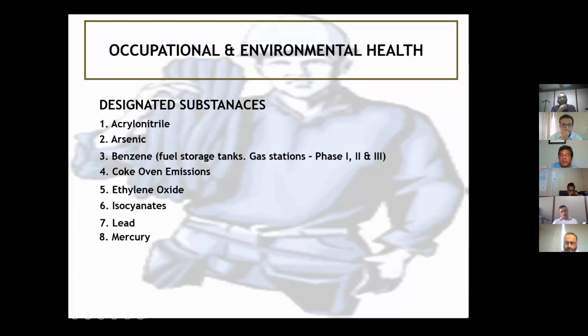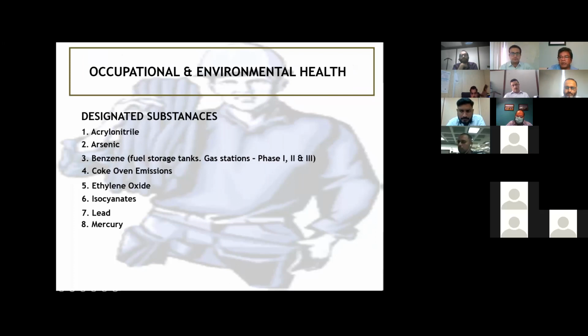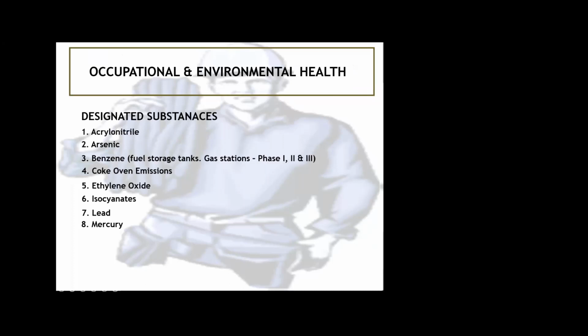People have been working in those labs, and the mercury gets trapped into the drains, let's say, the P-trap, in other words, so it does not flow with the water. If you open a trap, the mercury might be sitting there for the last 40 years. We have found mercury penetrating through the floor tiles, and sometimes we have removed the floor tiles and found mercury underneath. Silica is common. Any concrete, any sand, any cement related products would have silica.